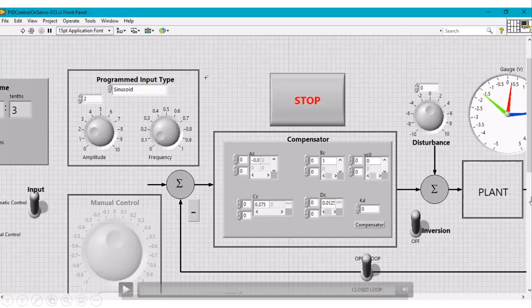So this is still open loop. Why? Well, there's no feedback. There's no measurement. I mean, we are capable of measuring, but we're not using the data. So let's see how well it does. Remember, what we're doing is we calculate. We know what kind of motion we want, so we have a desired motion here, and we're going to calculate the voltage that we will need to get that.